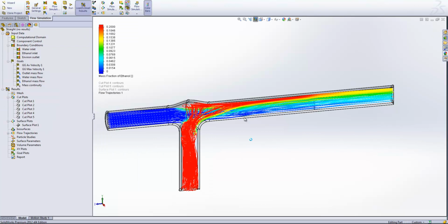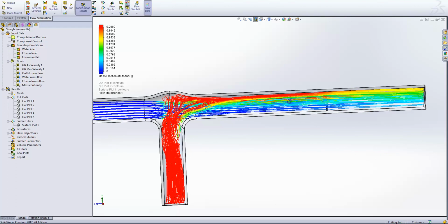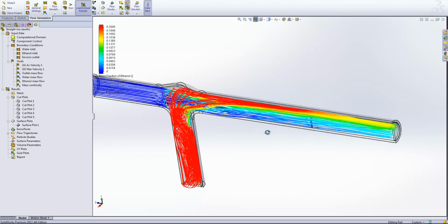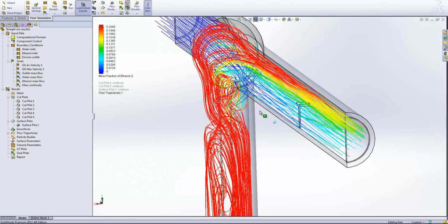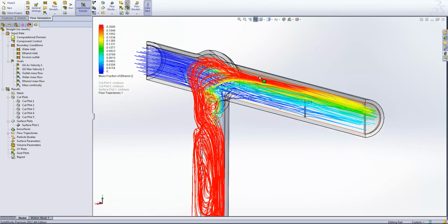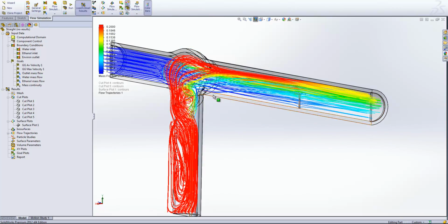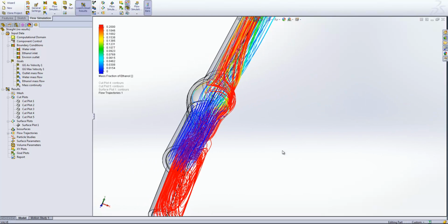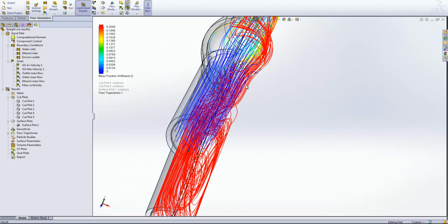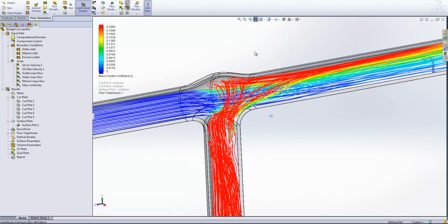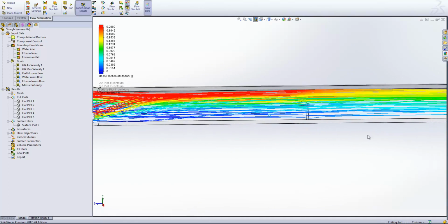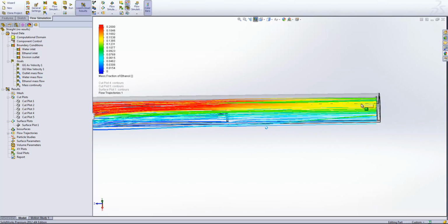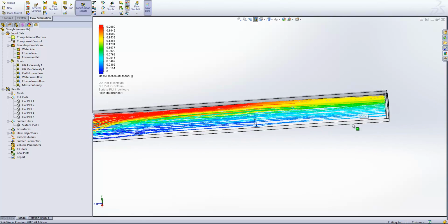And using the mass fraction, you'll see it looks very, very similar to the cut plots that we've had, but we can use the mass fraction value to paint our streamlines, and we can see how well mixed they are and how they are mixing here. So we can see how the flow is wrapping up around the top and staying in this pocket in the top section along the inside of the tube until we reach the end, when we're starting to get a little bit more mixing.